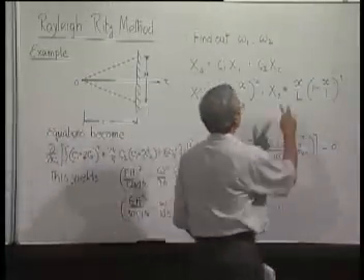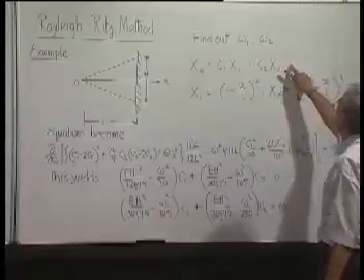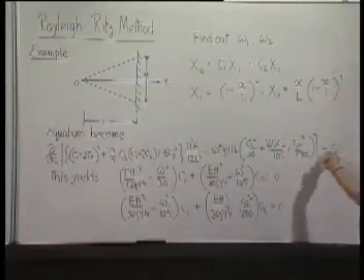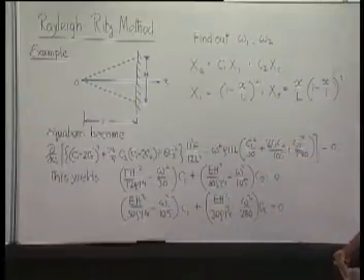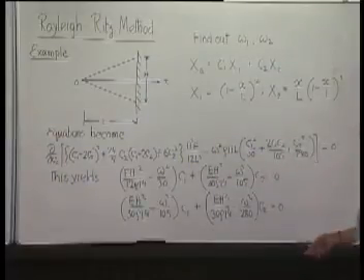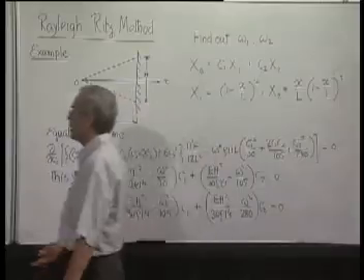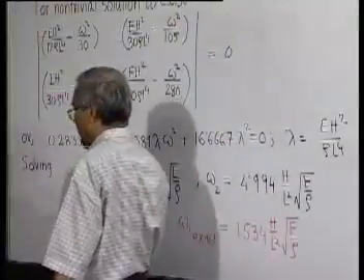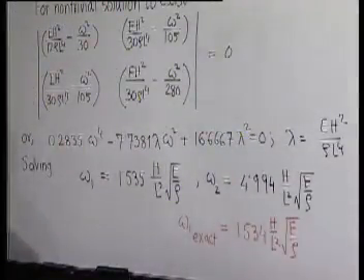We could find out even higher frequencies, only then it will be necessary to add one more term here like C3 X3. Obviously, computation will be more. There will be 3 equations in C1, C2, C3, and the determinant will give rise to a third degree equation in omega square, so it has to be solved for the root.